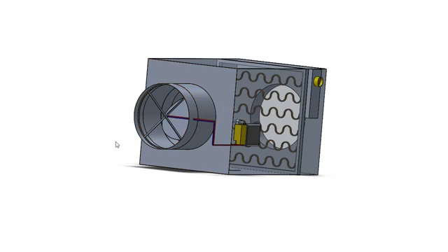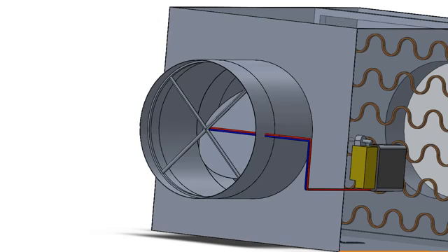On the back side, looking in through the inlet here, you can see these tubes which are coming from the controller, and entering into there and connecting to this weird cross shape. This is an airflow sensor, and it's basically measuring the change in pressure across this device, and from that you can average this and calculate the air velocity or flow rate into the VAV box.